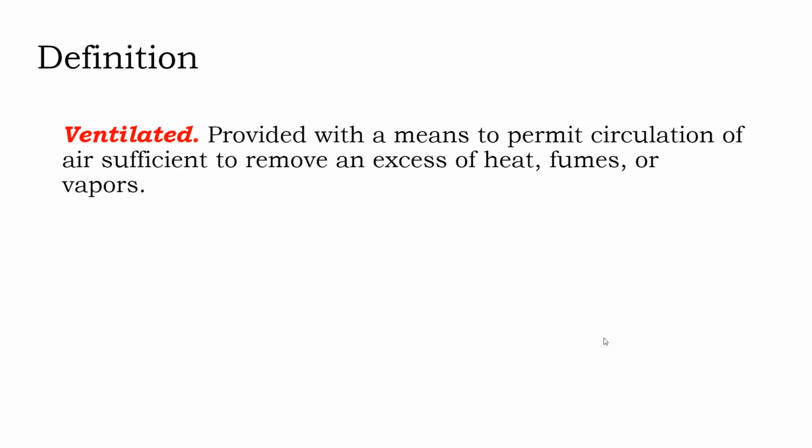Ventilation. So there's two times when you need to ventilate a battery bank. The first is unsealed batteries, where the ventilation is obvious. The second time is when your battery starts to get large, like in a commercial storage system, or maybe a very high end luxury home system. Once you get to be more than 100 gallons or so of electrolyte, even if it's a sealed battery, you'll need to have a ventilation system.